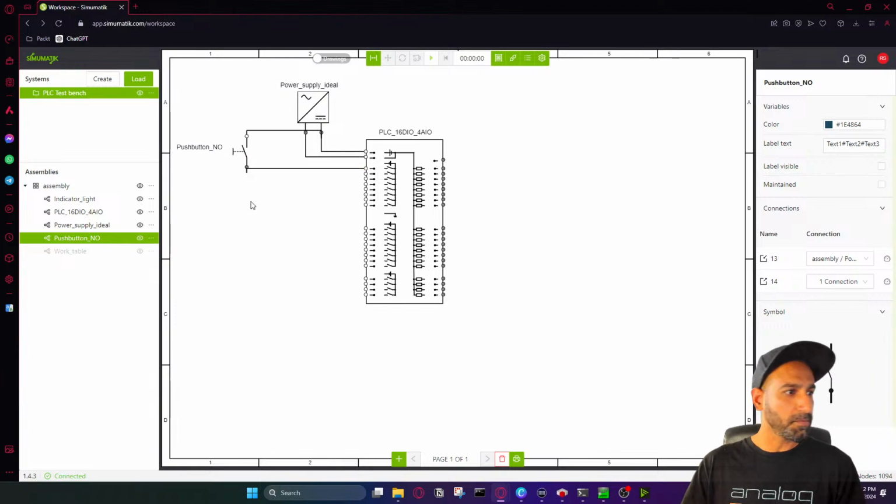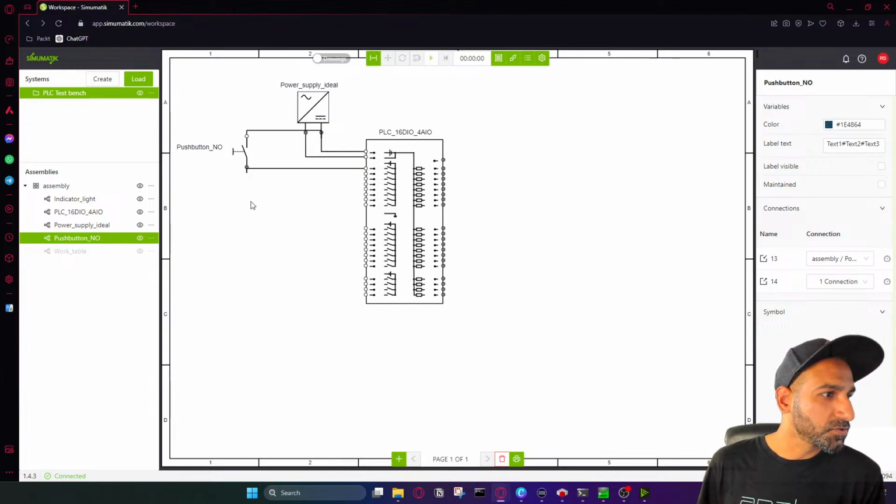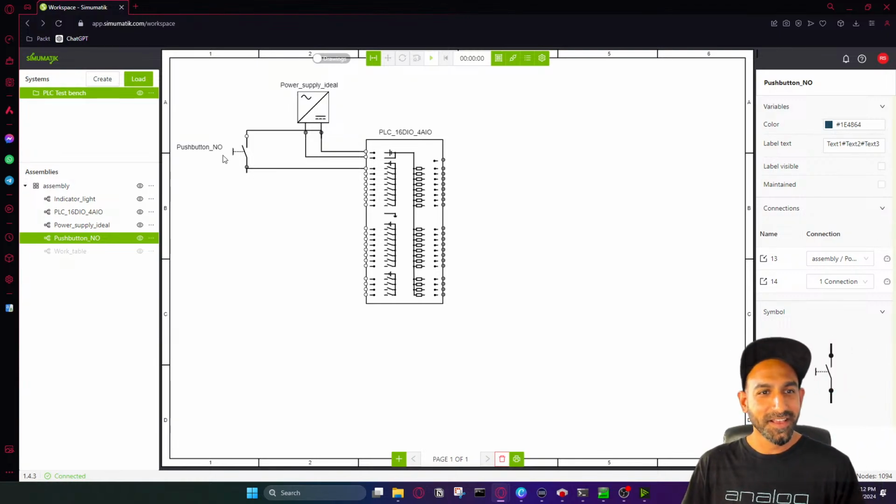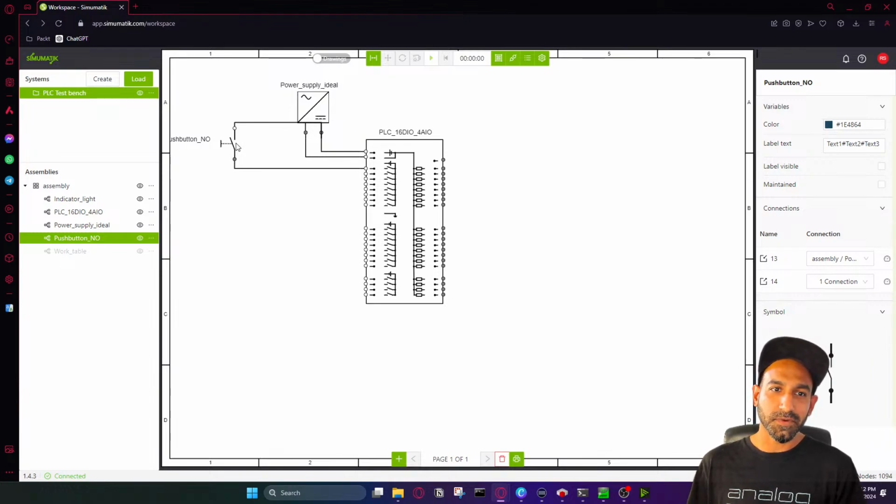So we have a comment from Marcin. Usually even in Simulator there is no power supply connection. I'm delighted. Thank you, Marcin. I'm happy that you're delighted, because here it's a much more realistic way when you are wiring up the component. You also need a power supply, and if you want you can also add some fuses, some MCBs, and you can set the rating of your current and it will trip on that current.